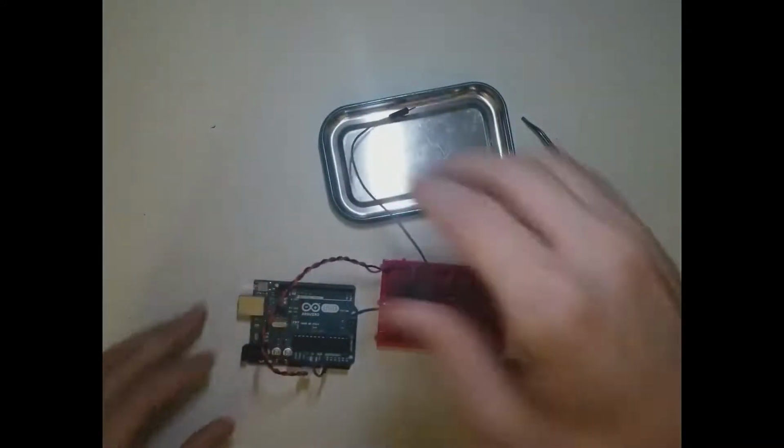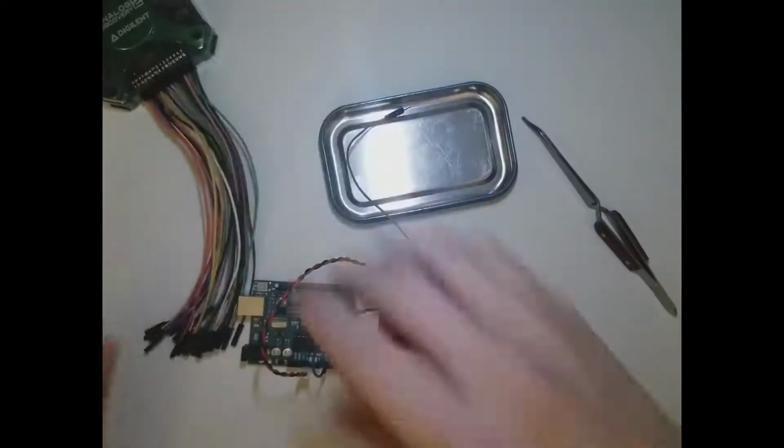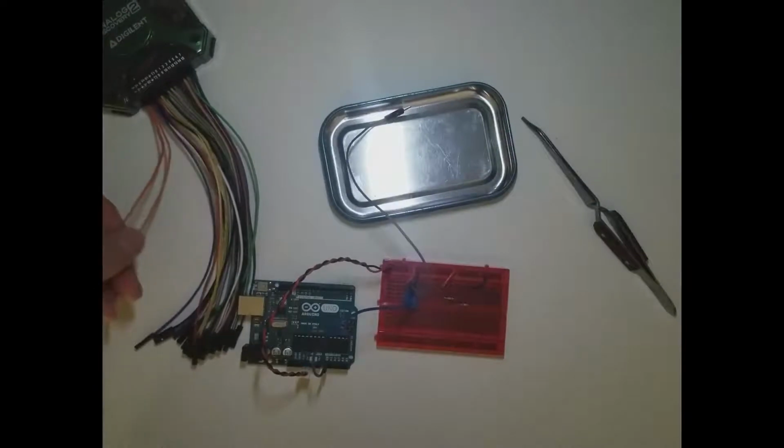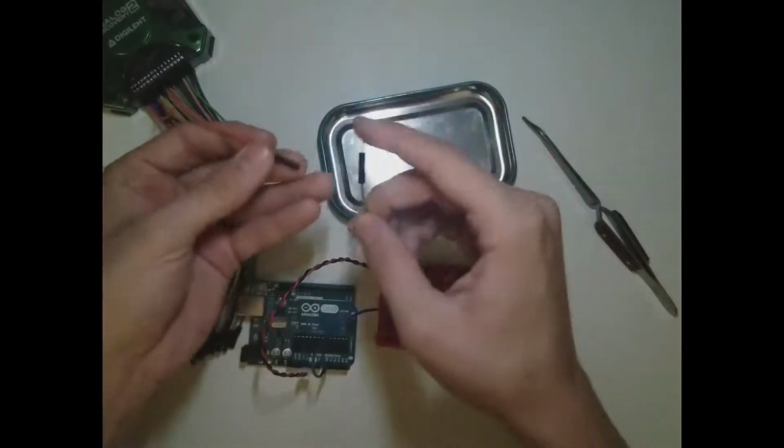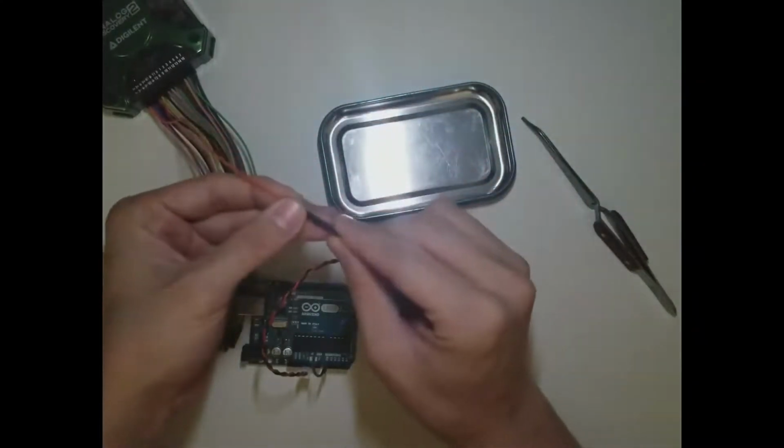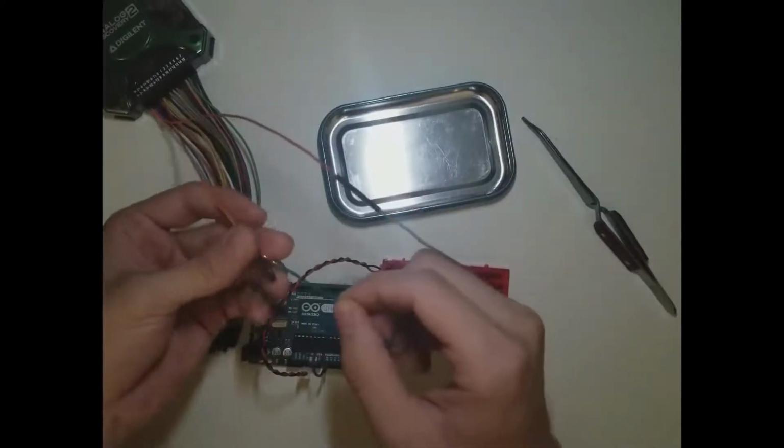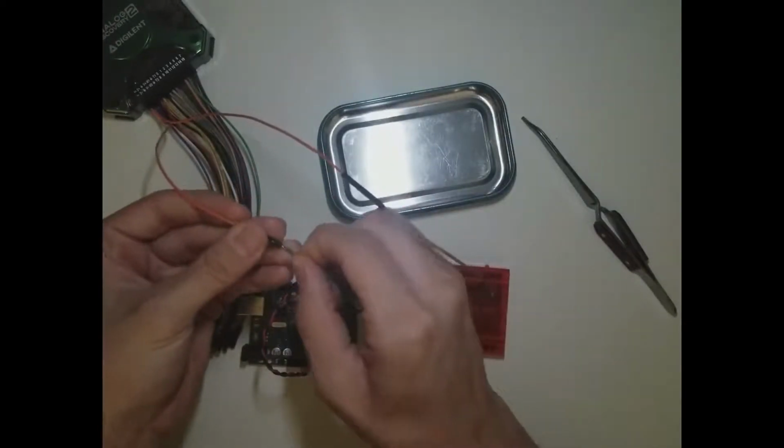And just to make sure that our Arduino is telling us data that makes sense, let's use this scope to verify everything. The orange wires are the channel 1 for the oscilloscope. One of the wires has a stripe, and that's going to be the negative terminal that you want to connect to ground. Now let's write this program.